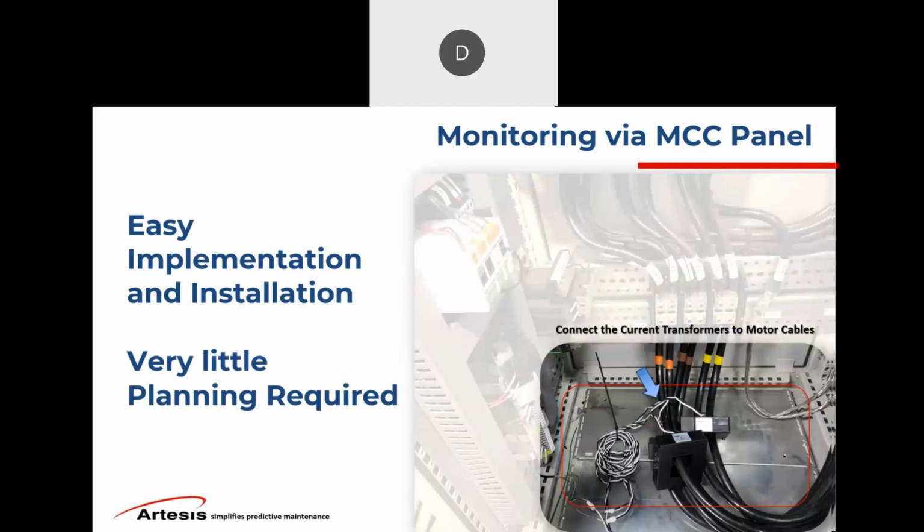These are custom made for Artesis and this application. So we provide you with this cable here with these three plastic clips, and each one of the CTs is a clamp-on CT. So you don't have to remove these big heavy cables and possibly cause a fault by not tightening them correctly or whatever. We just simply clamp them on. There's an arrow on them, point it towards the load.